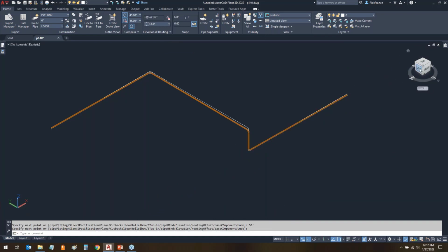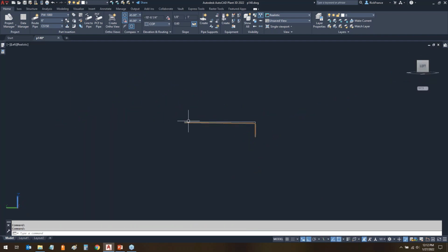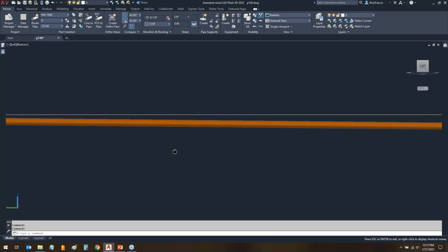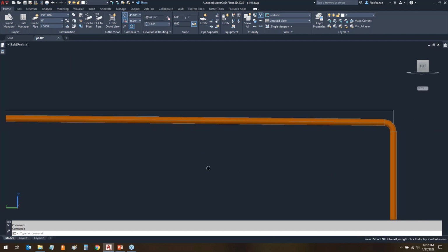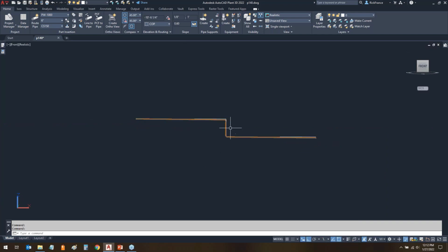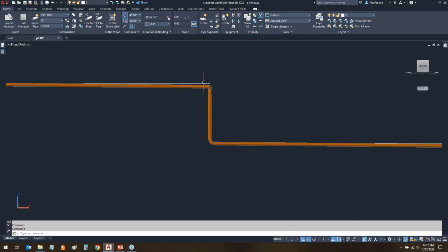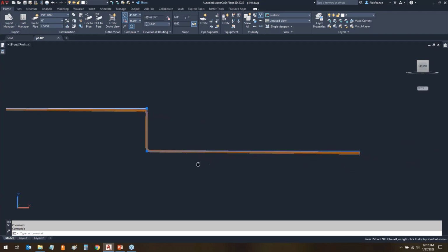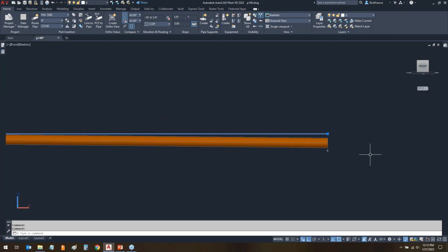So basically you can see from that line that I drew originally, I'm sloping 1/8 inch equals a foot, that whole 50-foot line. Over here, I'm right at that 10-foot. If I select this line, you can see I'm right at the 10-foot and then starting the rest of the slope down for the rest.